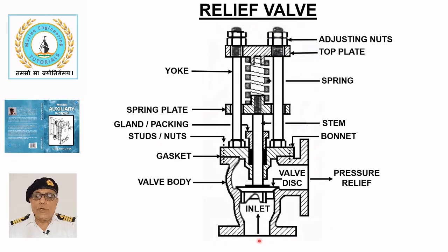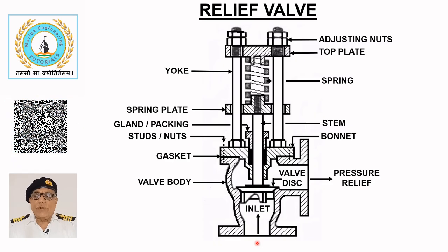Under normal working conditions, the relief valve remains seated. If the pressure rises to the set value, the relief valve lifts and releases fluid continuously until the pressure drops again. Malfunction of a relief valve may be caused by incorrect settings, deposit on the valve seat, or damage to the seat. Relief valves should be inspected at regular intervals.